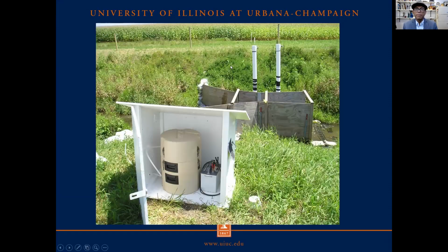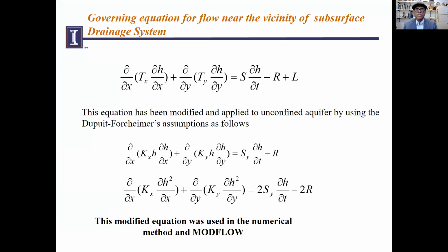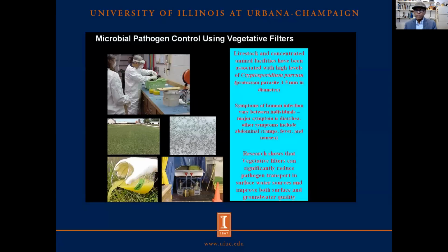We do lots of field measurements, automatic monitoring stations, automatic water collection systems, and we do lots of mathematical modeling to define the subsurface drainage water, the quantity, their interactions, along with the water table depths on the field, the river flow, and all those kinds of things. Some of the models that we use heavily are MODFLOW and many others that we have developed.